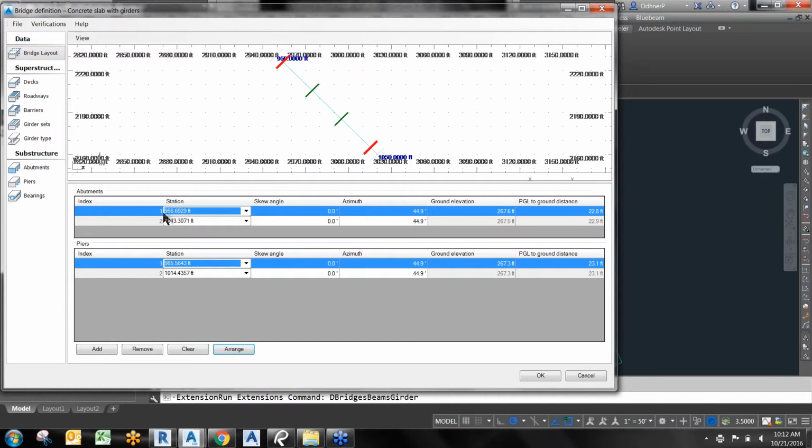You'll get a lot more information in Civil 3D, but through the extension, this is pretty much all we need for our Revit model. So here we have the arrangement, and here you can actually type in the actual stationing. And I know that our corridor needs a little bit more breathing room here, so we're going to put in 975 station.